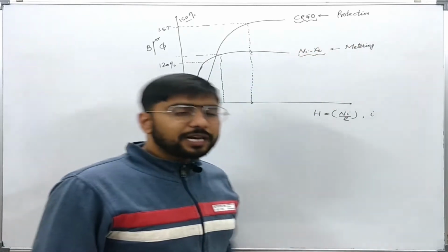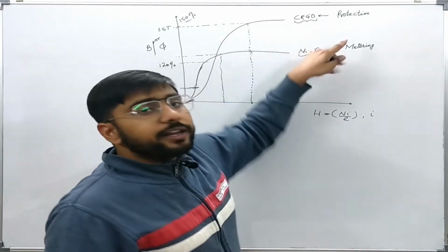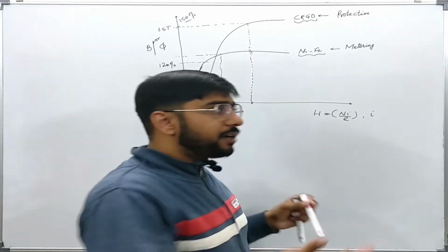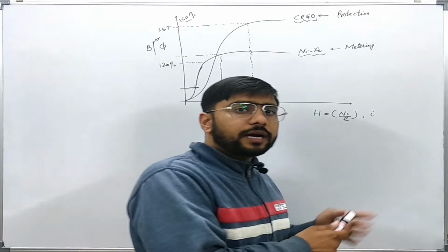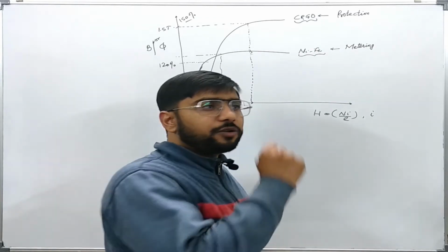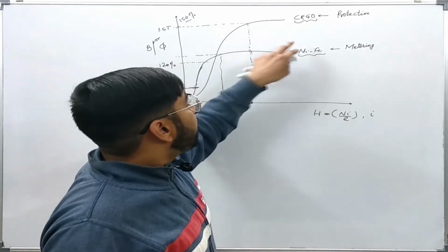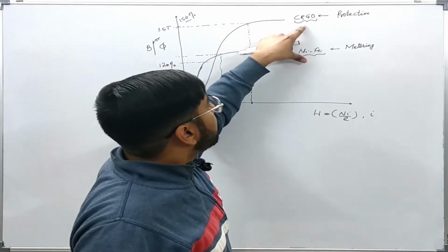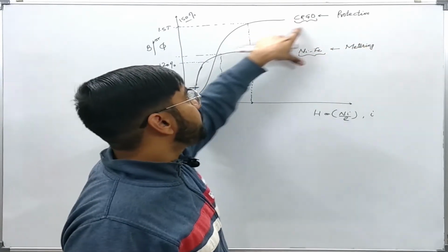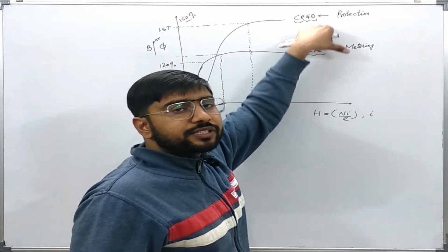Now, this is the part in which we have seen various materials for the construction of two kinds of CT. Similarly, when we will study the transient phenomena, we will see that these materials may not be simply enough for our purpose. We might have some other manufacturing style or design, like we might have to use some air gaps to introduce linearity through the air gap. Even when we use this material, the relay might not get the faithful transformation during the transients, so we may require some special kind of construction.